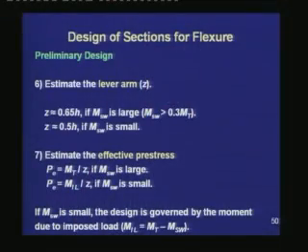We assume that the pre-stressing force is staying constant, and hence the moment applied is equal to the pre-stressing force times the lever arm by which the compression shifts from the CGS. From this concept, we can calculate the effective pre-stress equal to the moment divided by the lever arm.